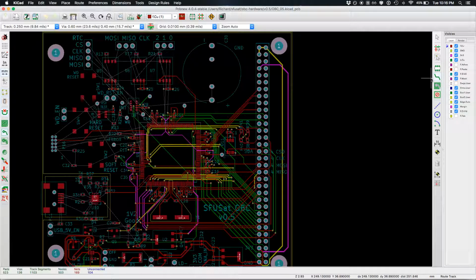So go to your wire tool, and then if I press 1, I'm on top layer, 2 is ground, 3 is 3v3, and 4 is bottom copper. So the top and the bottom copper layers, we're going to use exactly like we've used them in the past.